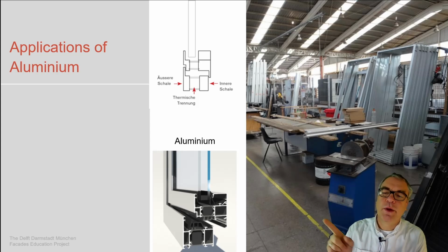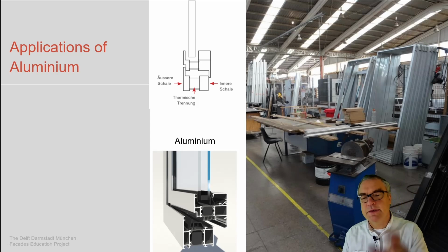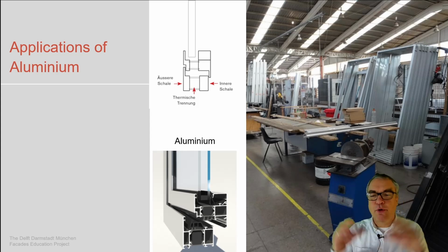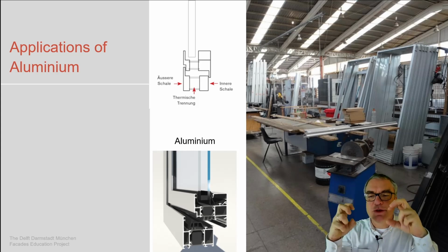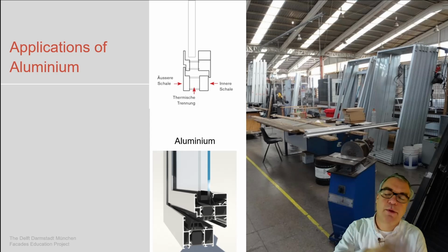And to do so, we create this additional thermal break. You see the thermal break which happens here, which is a plastic component being integrated into these two extruded aluminium profiles, or an extruded plastic profile being added to the extruded aluminium profile, brought together, having these sharp edges which are then clamping them and keeping them in position, and by that being a thermal break within this system.